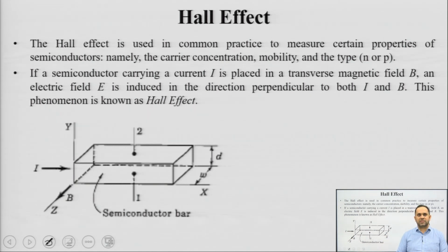And both these charge carriers are complementary to each other in terms of their charge carrying capacity or direction of movement. We also identified that in any semiconductor at any given point of time, you can have up to two different mechanisms of charge carrier transport. These are known as drift and diffusion current.